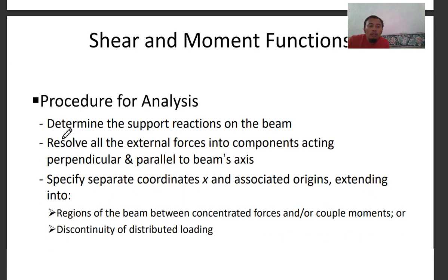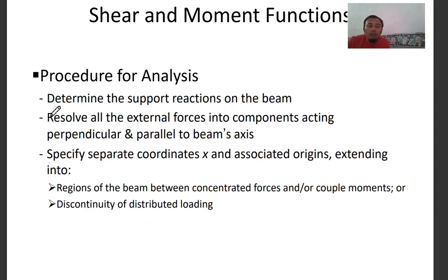So, procedure for analysis. First, you need to determine the support reactions on the beam, and then resolve all the external forces into components acting perpendicular and parallel to the beam's axis, and then specify separate coordinates x and associated origins extending in two regions of the beam between concentrated force, or couple moments, or discontinuity of distributed loading.